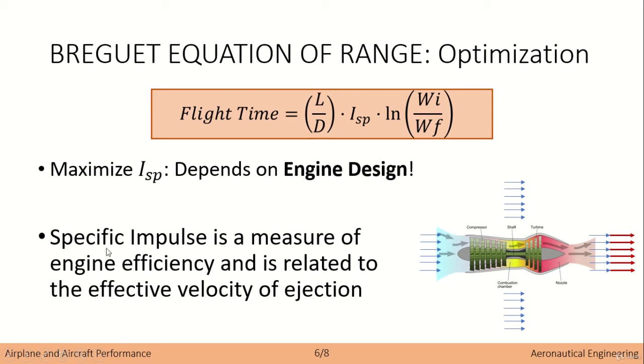So we just get more velocity due to the air going through the engine, right? So specific impulse is just a measure. It is multiplied by a constant, but it's just a measure of the relative velocity increase, okay? So in this case, you can see that this velocity would be the velocity at the end, and this velocity is the initial velocity. You just make the calculation of the difference between exhaust velocity and initial velocity, and you get kind of the specific impulse.